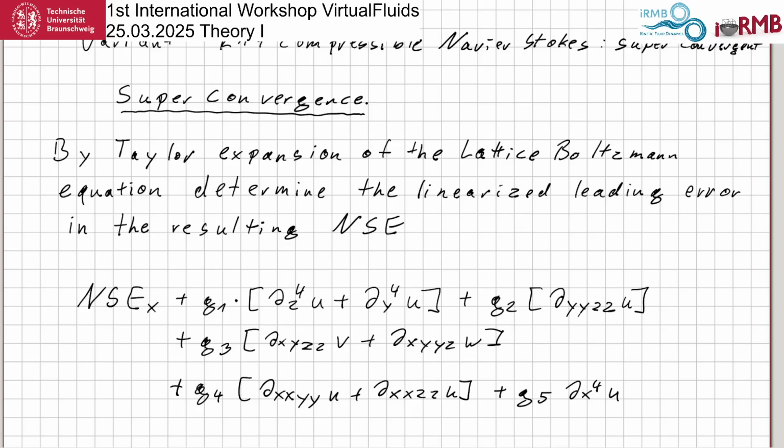So actually getting these equations requires doing the Taylor expansion, putting the Navier-Stokes equation into itself again and again until you get all these terms out. And the reason why there is no time derivative in this is whenever you have a time derivative of a velocity, you can substitute the Navier-Stokes equation again, in order to eliminate it and put everything in the spatial derivatives, right?